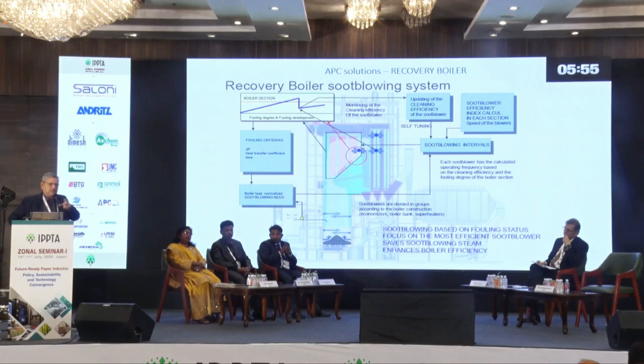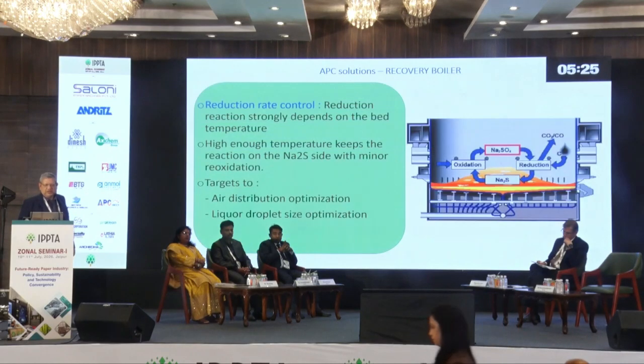How I will operate the soot blowing, in what areas, at what speed, with what steam consumption, given the fouling characteristic of the recovery boiler ash which is generated, decides how you spend the steam. So you have to optimize the steam which is used in the recovery boiler. That is why it is put as a separate one.